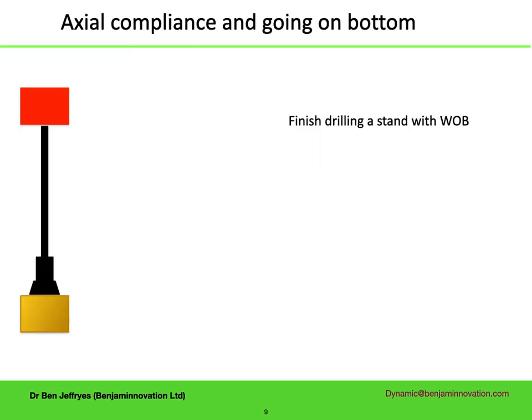This is what happens every stand. When the block reaches the bottom of its travel, more pipe must be added. Here's where the block is. What very frequently happens is that the block is immediately raised, so just before it moves up, there is full drilling weight on bit.